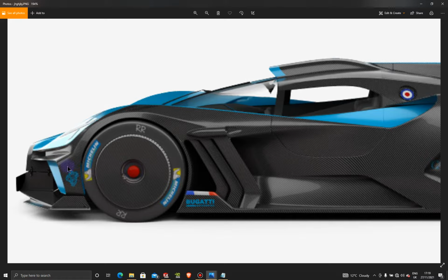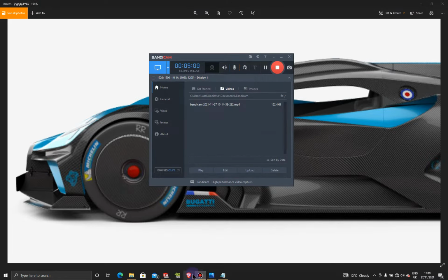And then to do that, we need to determine this line here that jumps out, and then we're going to attach some 3D points on this surface here, which we will come out, then we will connect to this line, which we will determine. We won't see this line as it is on here on the blueprint, so we kind of have to guess on that one, unfortunately.